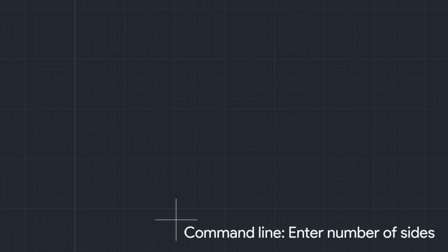Okay? So, now, when I create a polygon, first, look at the command bar. It asks for the number of sides. And if you make it 4 sides, what does it make? Square. Obviously. But since square is so overused, let's try pentagon. 5.